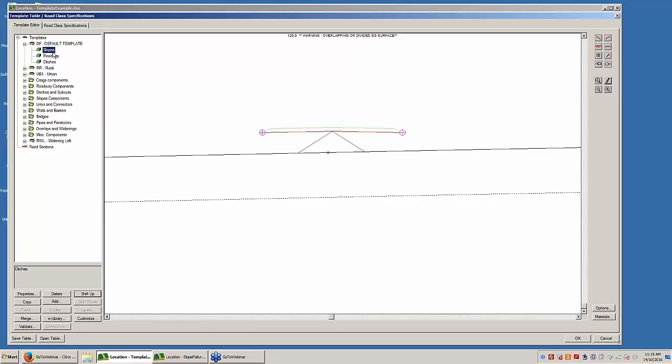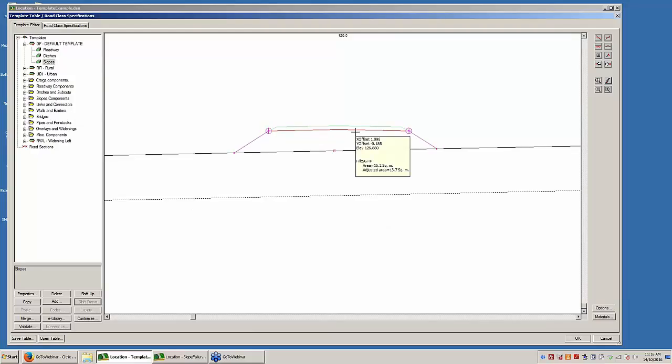So the usual order that you'd expect is the roadway, then ditches, and then slopes. I'll talk about more complicated stuff just now, but that's what we call the merged surface concept. It follows construction sequence.